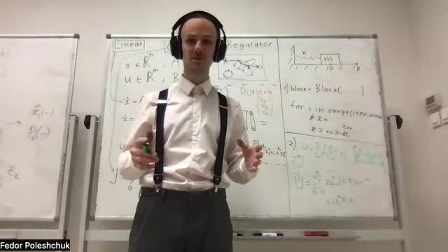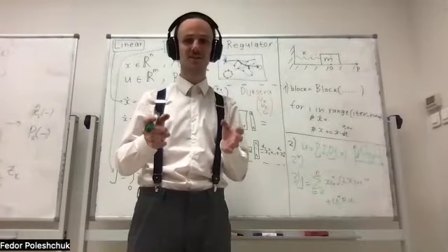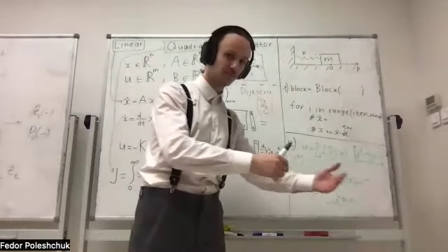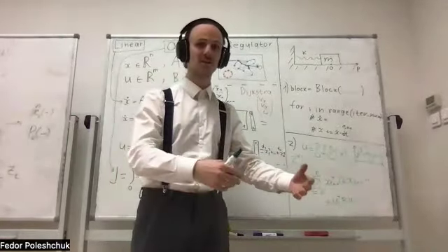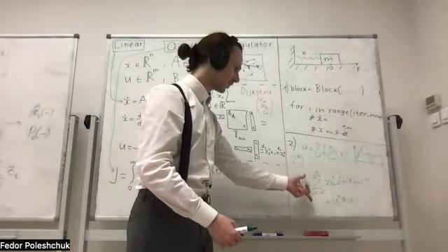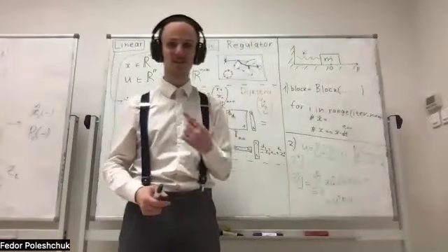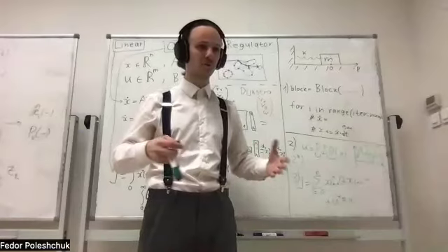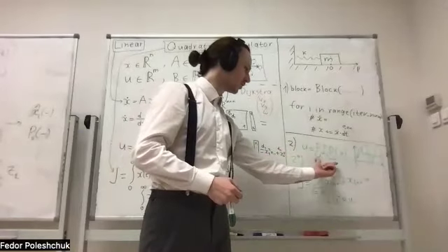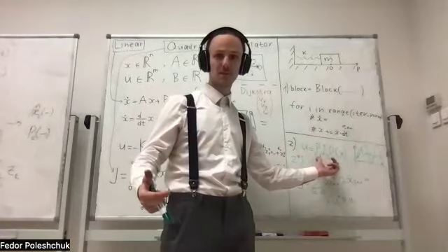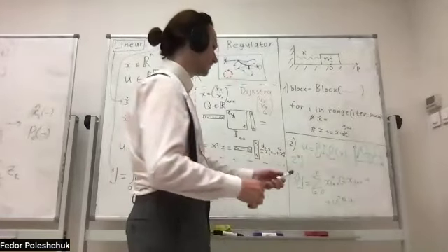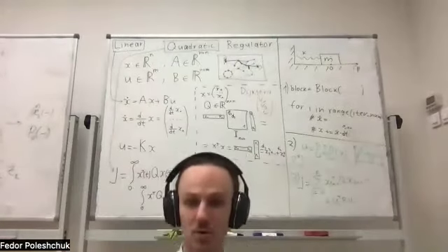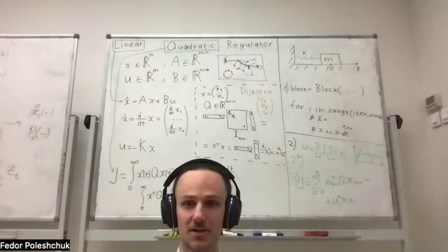Here, each word is important: cost of the state action trajectory. The state trajectory is the sequence of the states, and the action trajectory is the sequence of actions. By calculating this whole sum, we will get a single value that will characterize how good or bad the exact controller with the exact values of coefficients performs. And you can try out different values of P, D, and I and compare them in terms of the cost. You get the idea, right?